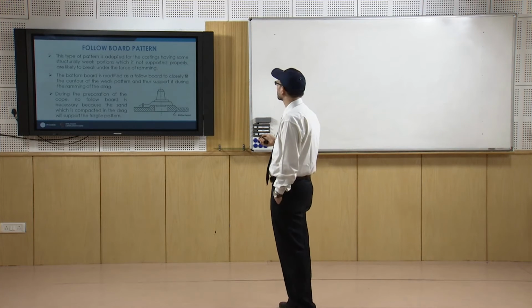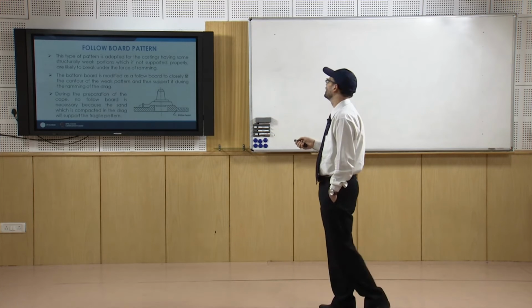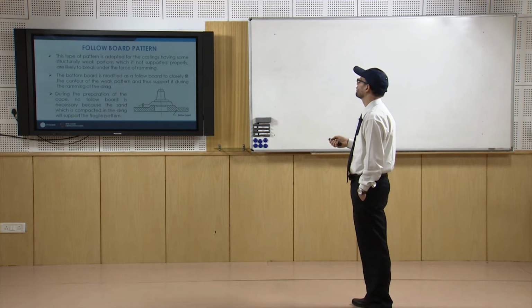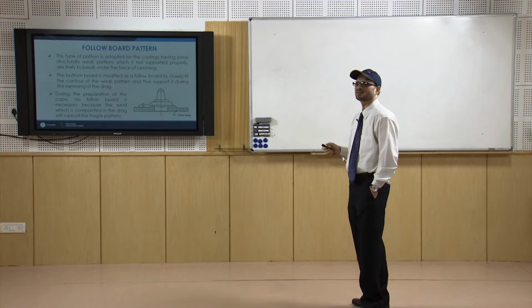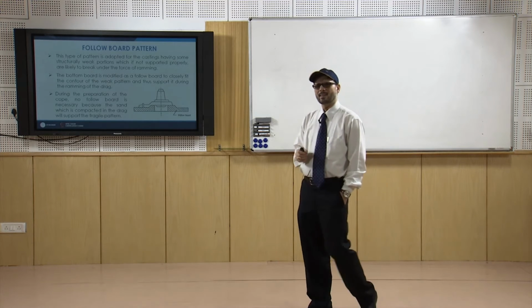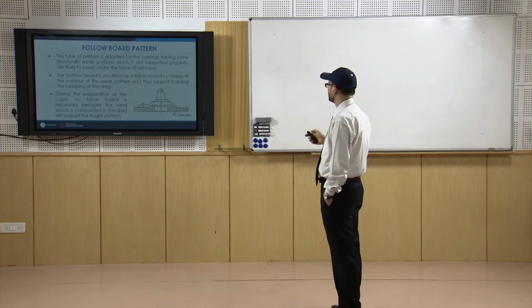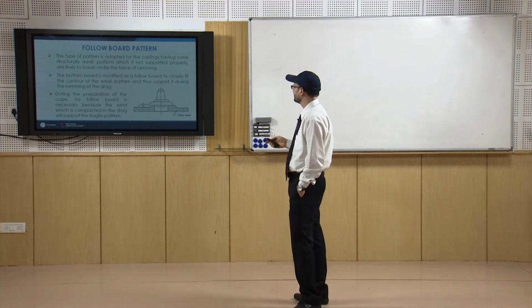So, it is adopted for castings having some structurally weak portions which are not supported properly and are likely to break under the force of ramming. So, in those cases you use this follow board type of pattern.